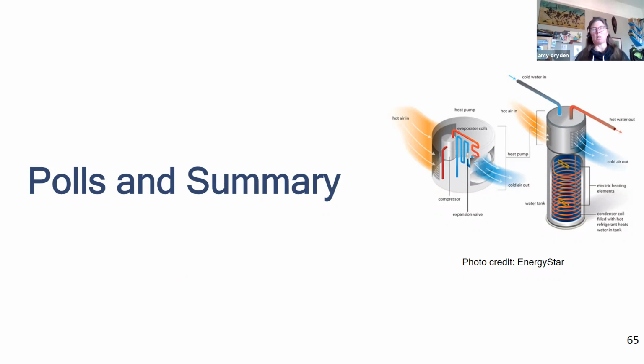Something I'll say about heat pump water heaters too is we just have to think differently about how we size them and operate them, because they do have longer recovery times than a gas water heater. And Amy, you might want to mention a little bit more about the temperature. So that storage with the mixing valve, I think that's a great combination to use that thermal storage through the peak times. Yeah.